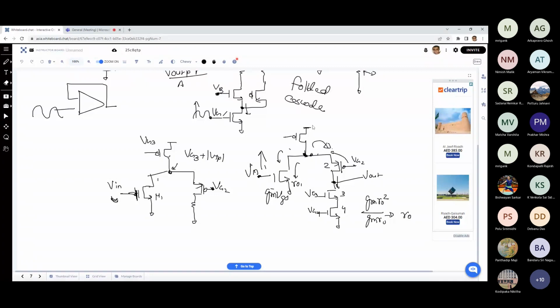It can be close to VDD, right? So in that case, I am not having a conflict between the output swing and the input swing. I can still have a relatively larger input DC level, or even larger swing. Input signal can go to a larger value also without jeopardizing the saturation region operation of this M1.